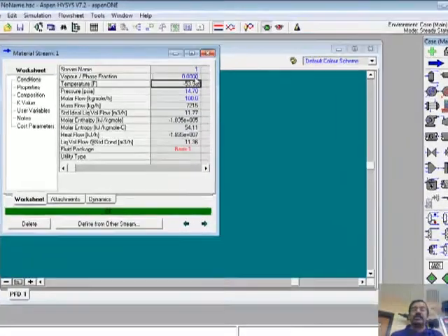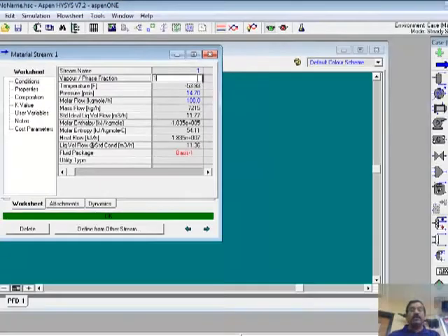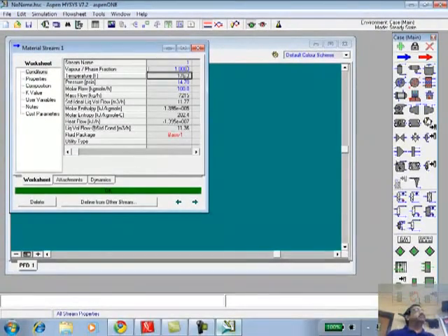So dew point. If I want to get the dew point, all I have to do is put 1, and that should of course be much higher. So this mixture is going to have a range of temperatures. What is the beautiful information that we get out of this? We know if the temperature of the feed is somewhere between minus 53 degrees and 176 degrees, you are in a two-phase regime. You are going to produce some amount of vapor, some amount of liquid. The composition will be different.